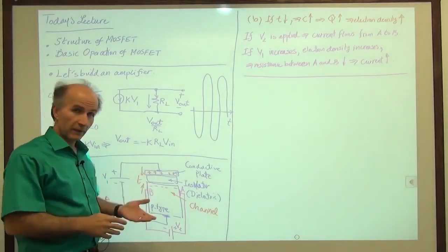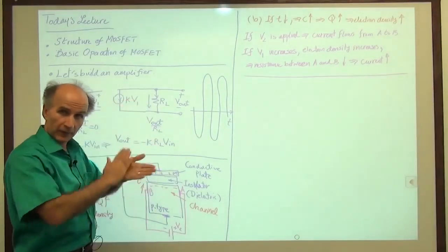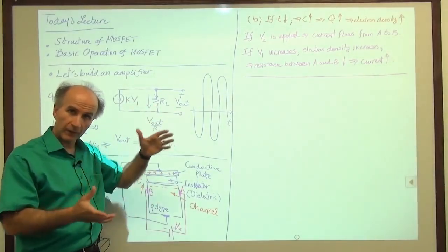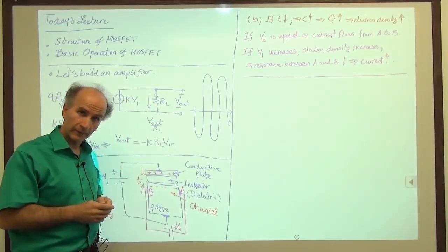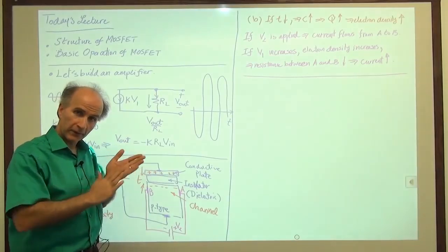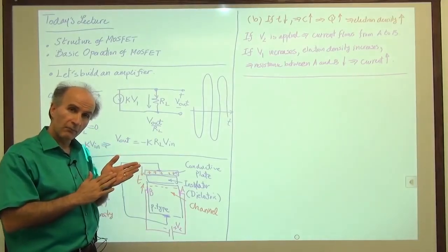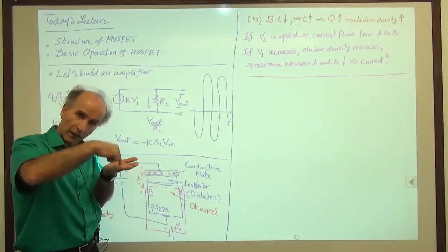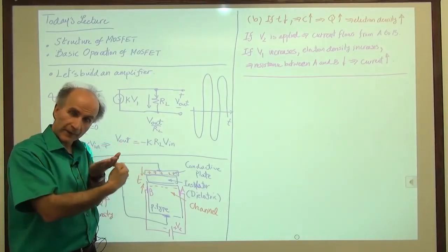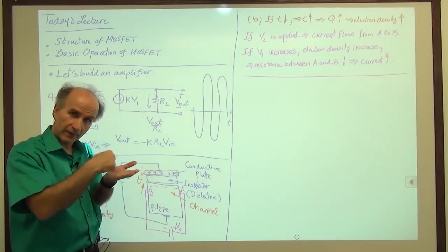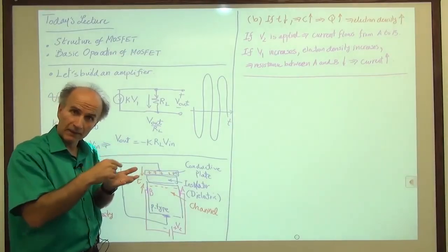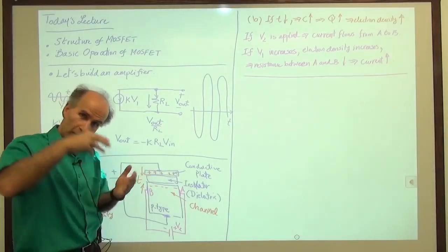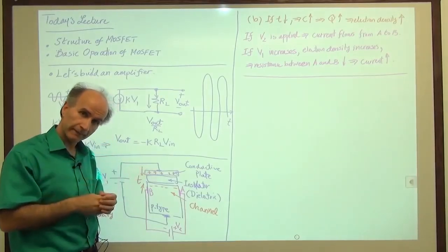But if we want to build this on that wafer that the guy was holding, that wide, thin wafer, we have some issues. On a wafer, we can only make connections to the devices from top of the wafer, like so. We can't go from the sides. We don't have access to the sides of all these millions and billions of devices. We can only attach from top.